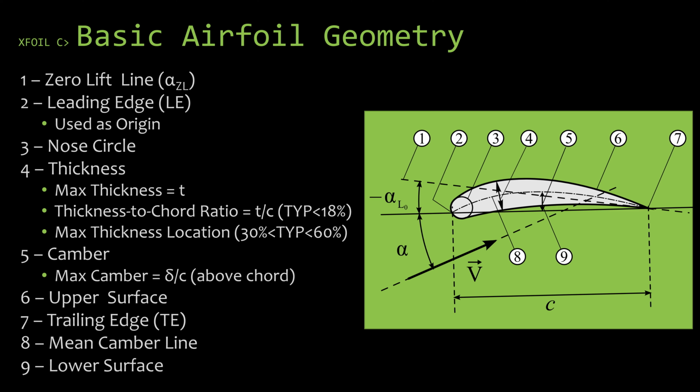And we already talked about trailing edge when we talked about leading edge. We talked about mean camber line. Just another parameter that's on the illustration, as you see, there's alpha, the angle of attack. That would be the angle between the chord line and the flow that's coming into the airfoil, the velocity coming into it. So it's just the angle between the chord and the flow velocity.